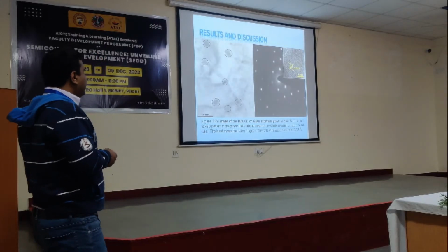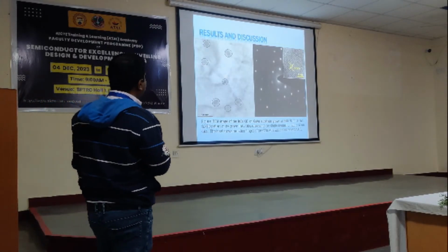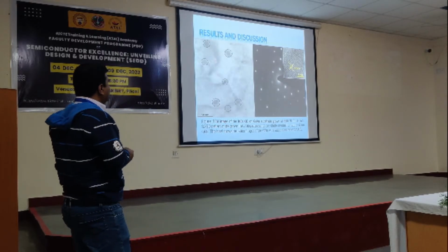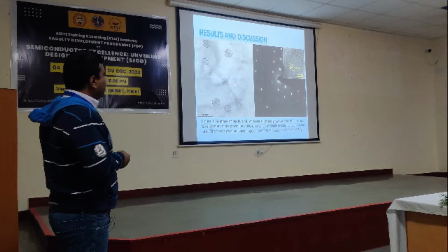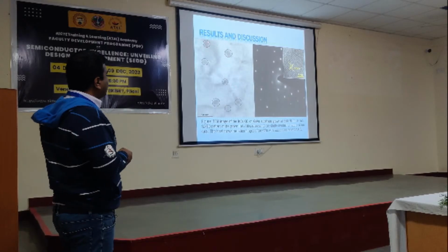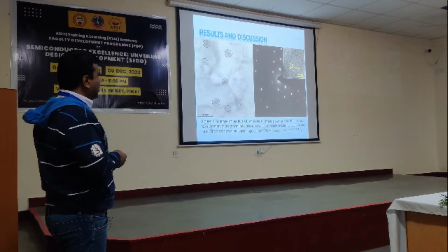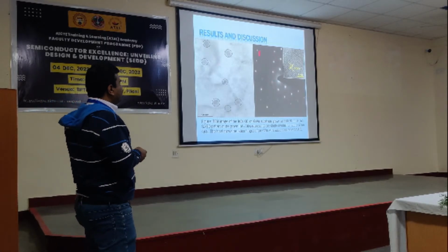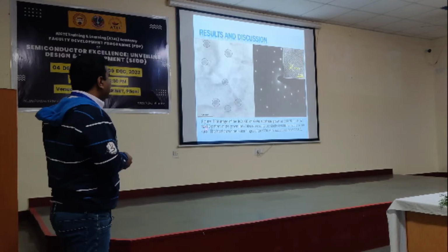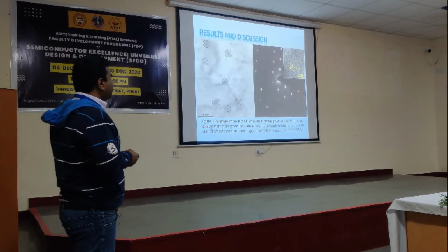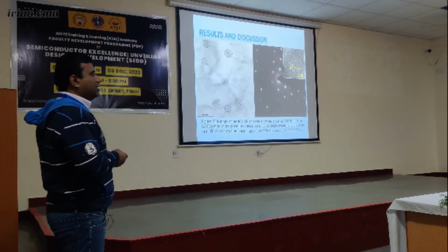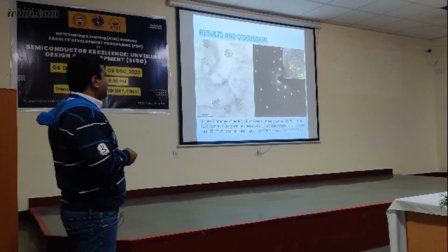Why? I will tell you in a later slide. Again, you can see here the TEM images, transmission electron microscopy. You see several bright spot patterns. Those spots are the formation of quantum dots, and this is the SAED pattern of the quantum dot. SAED means selected area electron diffraction. The bright spot pattern is nothing but your quantum dot, which ensures the single crystalline growth of the indium arsenide quantum dot.